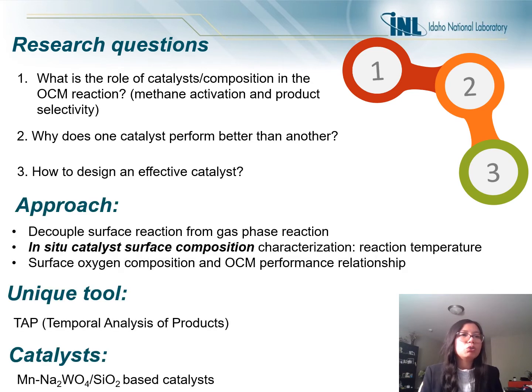To address these research questions, three approaches will be used. First, the surface reaction will be studied separately from the gas phase reaction in order to identify the role of the surface reaction and the role of the gas phase reaction. Secondly, characterization of the surface oxygen species at the OCM reaction temperature will be performed. And we're going to build a relationship between the surface oxygen composition and the OCM performance. In this study, temporal analysis of products will be used to help address the above research questions, and manganese sodium tungsten oxide-based catalysts will be used.